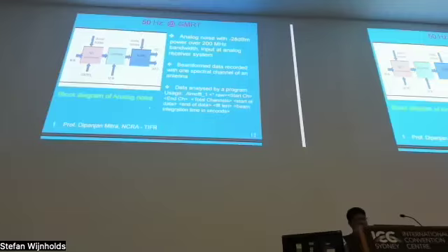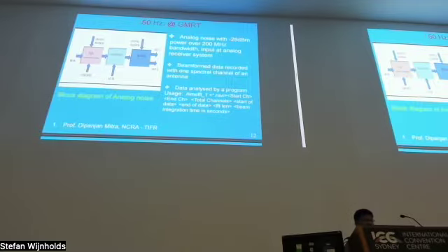In GMRT, we have tested the presence of 50 Hertz by inputting an analog noise at the analog receiver system. This analog receiver system has an inbuilt analog noise source, of 200 megahertz bandwidth, which is inputted. We have recorded the beamformer data for a single channel. Then we used a program written by Professor Deepanjan Mitra, NCRA, to analyze this data.